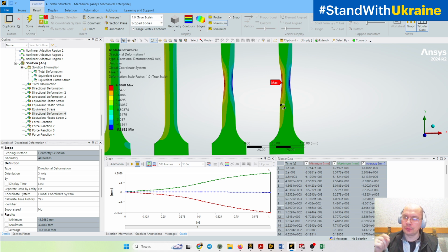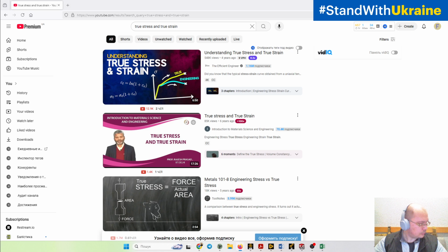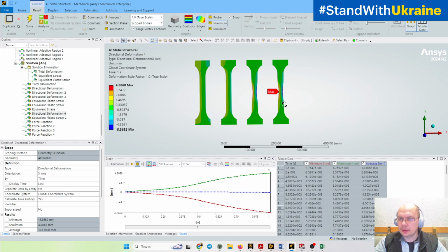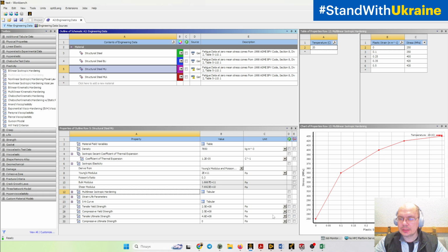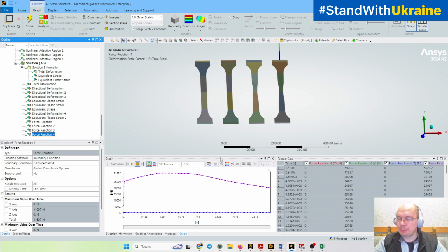And if you want real, true stress, true strain, you need to include as a minimum those formulas with logarithms, and mostly the whole information about the behavior of different parts of the specimen. So as you can see, with this type of data, we obtain the same type of behavior as in real life.